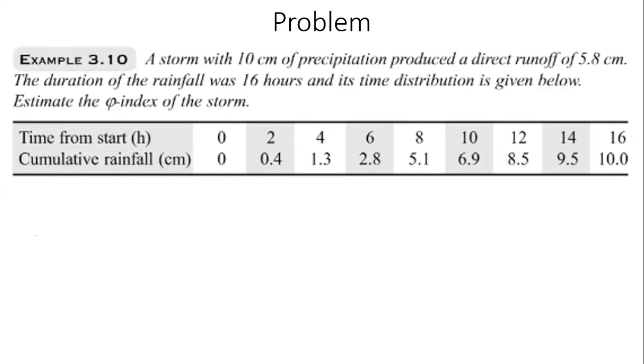This is not a hyetograph. This is a mass curve. So this information that you see is time versus cumulative rainfall. So it keeps going like that. At every delta t, the slope is the rainfall intensity for every delta t. Correct?